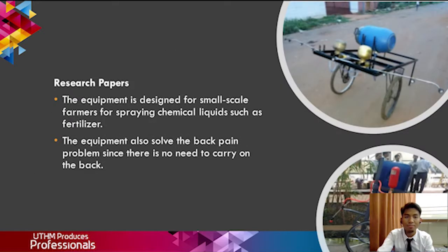Next slide. For the research paper part, occupational research on sprayer operation was carried out in order to identify a solution to create a tool that meshes the man-machine system. The aim of this research is to discover a way to reduce the operator's tiredness and suffering. Nordic body map surveys were distributed to knapsack sprayer operators. The operators experienced muscle weariness and soreness in the neck, upper arm, left leg, and foot.